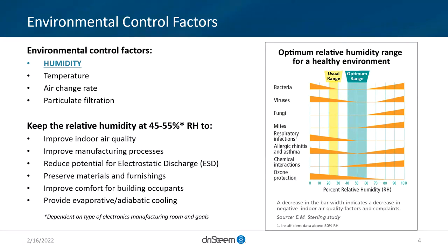The other thing, in a subcategory of humidification equipment, is the adiabatic section that provides sensible cooling. So we have this large heat load in a building from the process equipment, and can we benefit from sensible cooling is really that last bullet point. And we'll go a little further in depth on that. And obviously I want to preface that each application has different goals in mind. So maybe adiabatic is not the solution, or maybe you want an isothermal solution for one reason or another, and we'll jump into that.